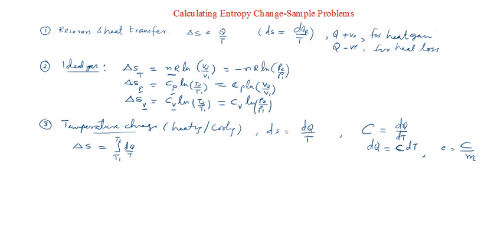Hope you remember this equation. We have done problems using this one with the law of mixtures, mixing one liquid with another liquid and finding the resulting temperature. We practiced some problems in the previous module, and at that time I told you that I need all these concepts later when we do problems in entropy. And here I am just using it again. So wherever you find dq, you will be able to write this as mc dT.